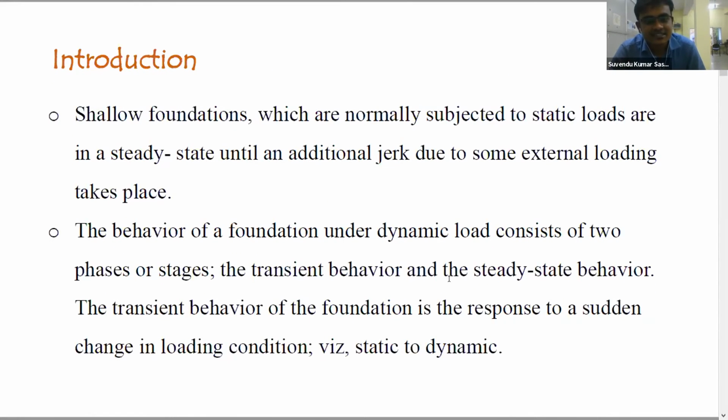Shallow foundations are normally subjected to static loads. As it is well known, in the case of dynamic load, there are two phases, transient behavior and steady state behavior. In existing literatures, it is found that when studying the behavior of a shallow foundation under cyclic load, the settlement of a shallow foundation due to fast load cycle is generally ignored, and after the steady state, settlement response is generally reported in literatures like Raymond and Comas 1978 and Das et al 1995. Hence, it is a matter of interest to observe what really happens during that fast load cycle, which is the main objective of this study.